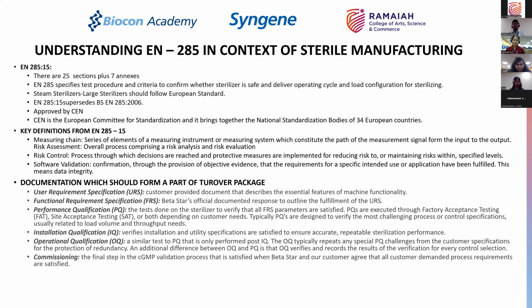And then what is called a site acceptance test and commissioning, you would take certain biological indicators, and you would place them inside the chamber and make sure that proper sterilization is being achieved on a given set of agreed parameters between the vendor and yourself. So that forms a part of the SAT and commissioning.